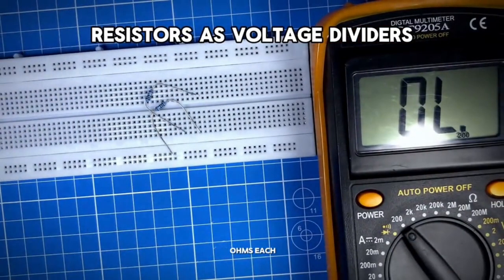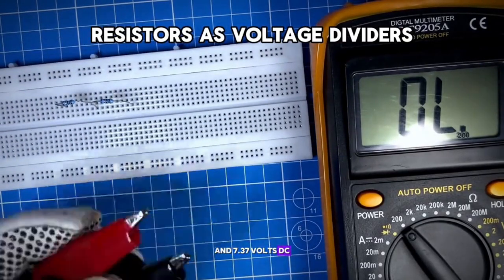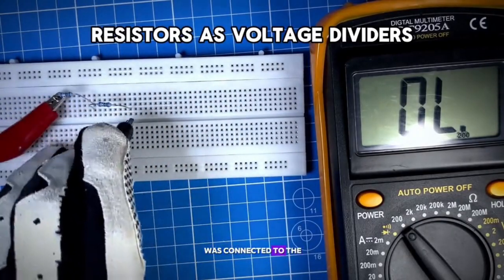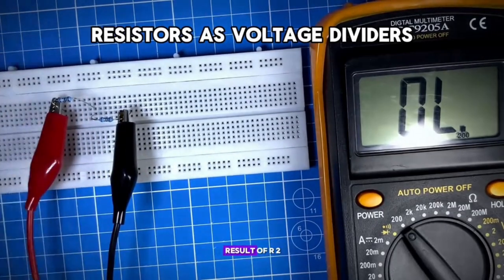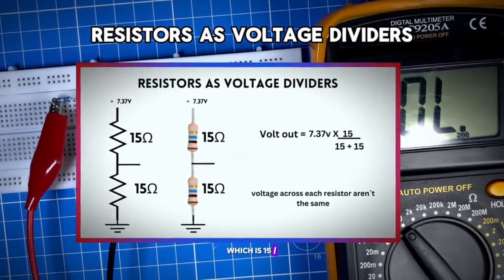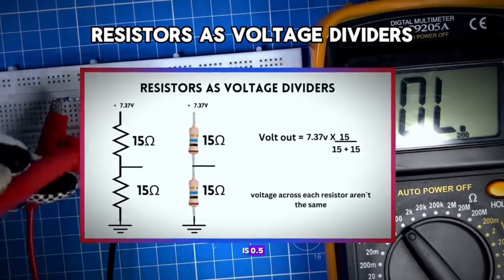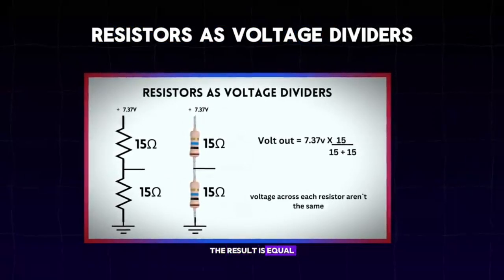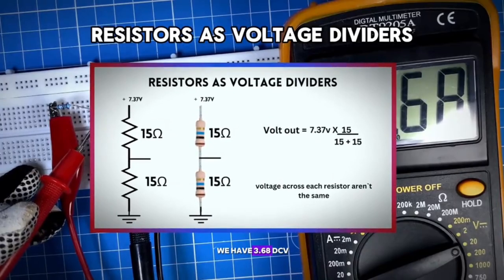These resistors are 15 ohms each. Then they are connected in series, and 7.37 volts DC was connected. The negative probe was connected to one end and the positive probe was connected to the other end. To know the Vout, multiply 7.37 by the result of R2 divided by R1 plus R2, which is 15 divided by 15 plus 15. So now let's say 15 divided by 30, which is 0.5. Then we say 7.37 multiplied by 0.5. The result is equal to 3.68 VDC. So as you can see on the multimeter, we have 3.68 DC volts.